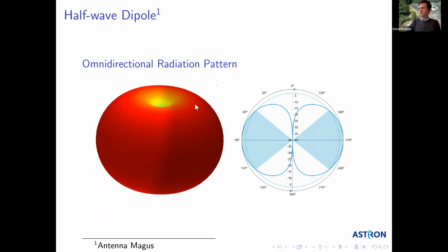So what you see here is you should imagine that you've got this dipole antenna right along the center of this null that you can see here. So this is the axis of the dipole antenna. And towards 90 degrees or 270 degrees, for all angles of phi around it, you have this maximum. Because remember, it's not just along a line that the current runs, but it runs on the surface of this dipole.